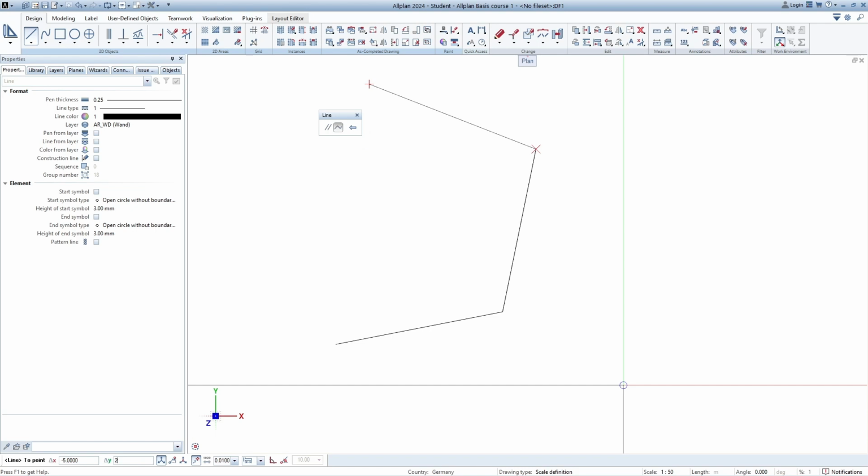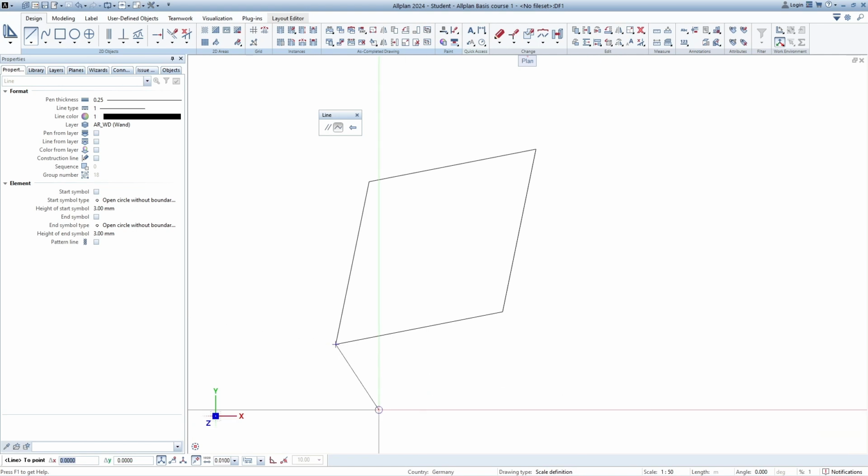So please keep that in mind, because sometimes this has been needed. Okay, but we are also very satisfied with what we are having here. So we have delta x, delta y, -5 meters, -1 meter, enter, delta x -1, and delta y -5, and then we basically closed our figure. So pressing enter on that one, and we have finished the input of the lines.